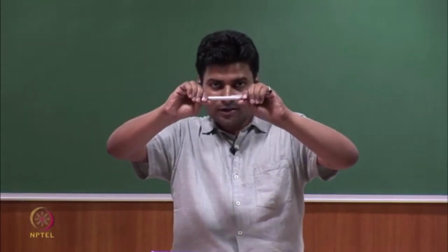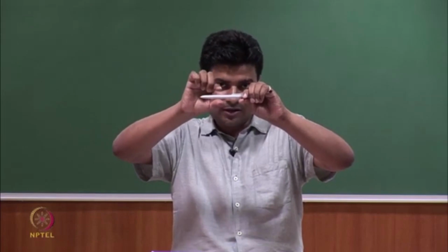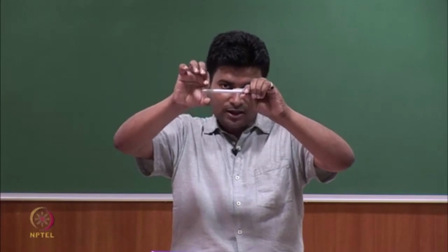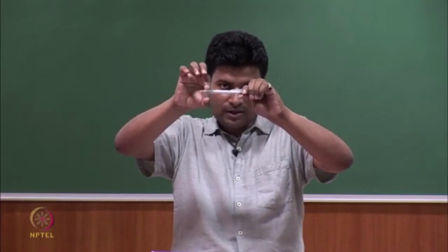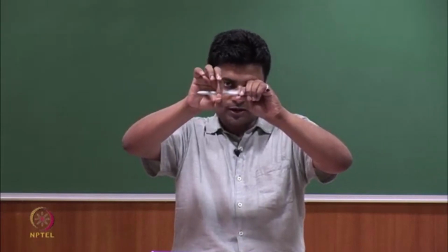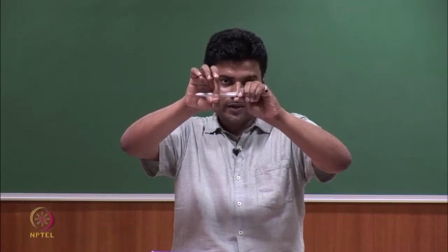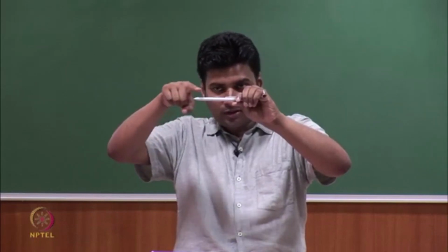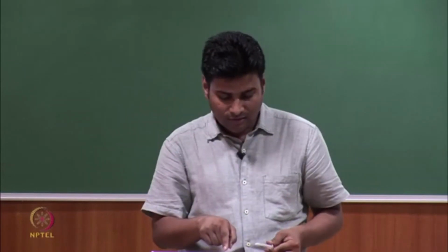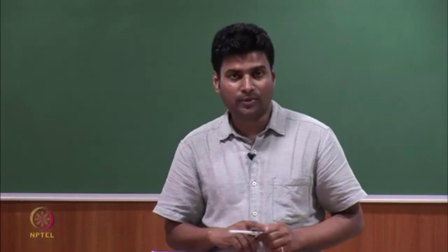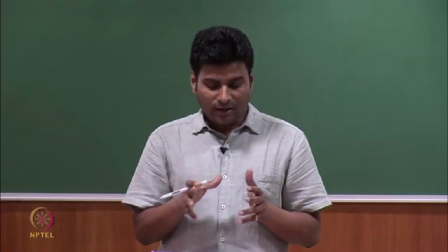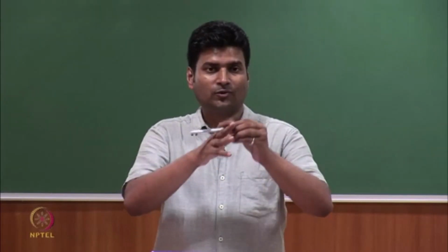When you stretch it, then due to Poisson's effect the radius will shrink, but because the end cross section you are holding it, its radius is not going to shrink, it remains as it is, but cross sections here, their radius is going to shrink, right. So, there will be non-uniformity in the radial shrinkage, and you will get exactly this kind of figure that we have here.